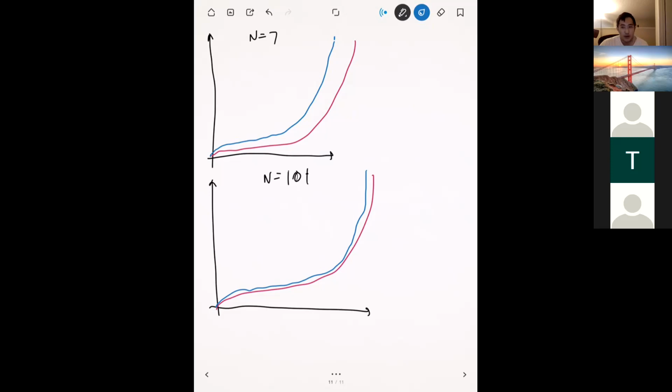All right, before we head off for today, I do want to leave you with one parting thought. What we saw for this example problem was a convection velocity that goes from left to right. In other words, the convection velocity is positive, so it goes in the positive x direction. The differencing scheme that we chose for this was backward difference. The reason for that was because it weighted our differencing on the upstream side, so we had more weight over here versus over here, and we get more information from the upstream side than the downstream. That's when the convection velocity is positive.